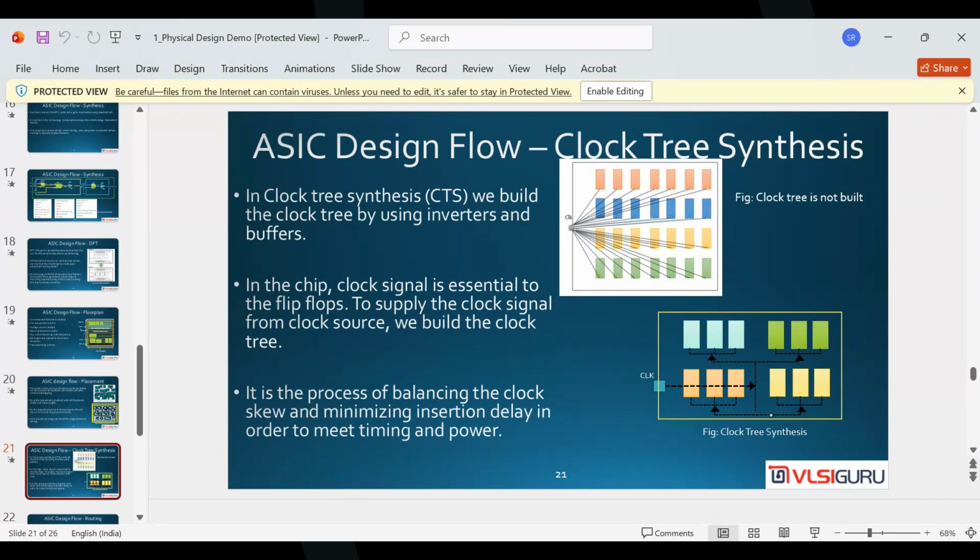If you see the second part, here also we are routing clocks to all the cells, but in a structured manner, in a tree-like structure. So this is the main trunk, and then we have multiple branches. It is basically an H tree, called the H tree algorithm. If you see here, it looks like an H. This helps us reduce the number of clock nets. It helps reduce the latency, I mean it reduces the longer paths, right? It also reduces the skew in the design, right?